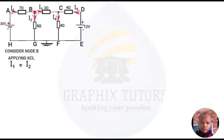Then I3 is also leaving, the arrow moving away from node B, so it goes on the right hand side too. You add the ones that are leaving together, and you add the ones that are entering, so they are separate. Remember, we're taking point B as our reference point. So we have I1 is equal to I2 plus I3. Is that okay?